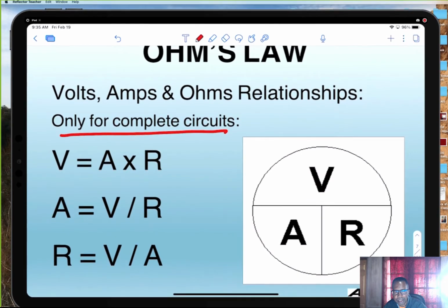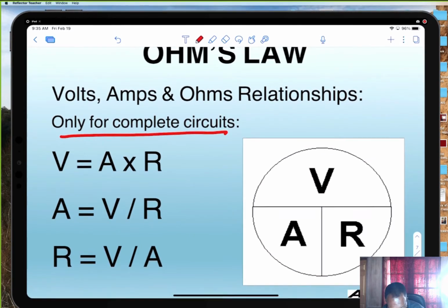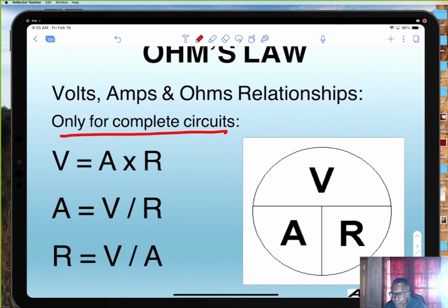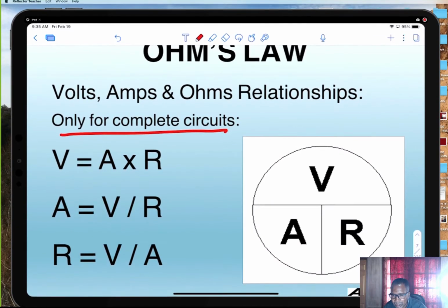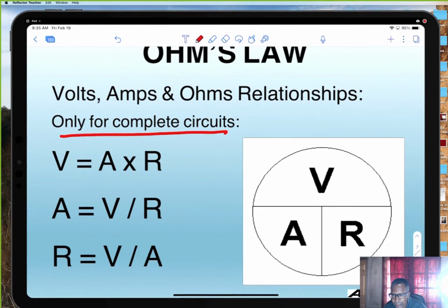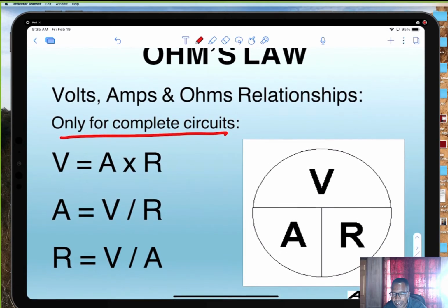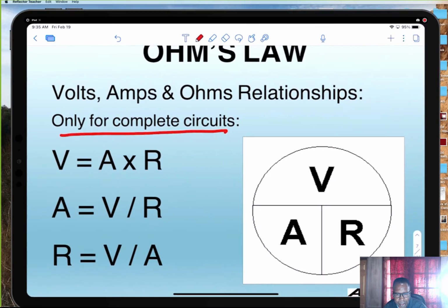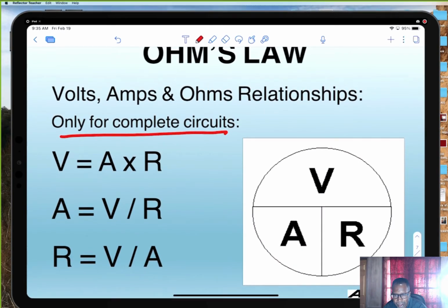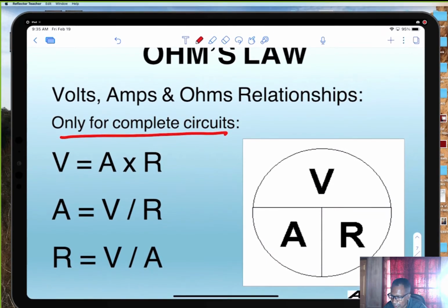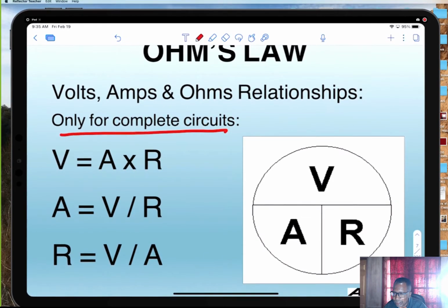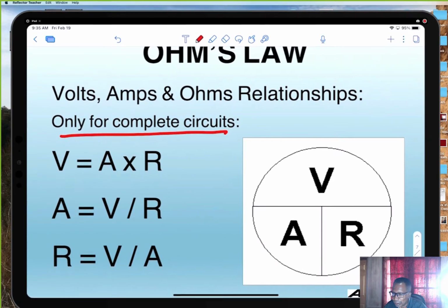A complete circuit is one that doesn't have any opening in it. Exactly. A complete circuit has a path from source to ground. You can have a battery, source voltage, a load device, and a complete path to ground. Now, obviously, in a real circuit, you have switches and other things too, but just a basic circuit has source voltage, a load device, and a complete path to ground. Missing any one of those things, or if it becomes open, you don't have a circuit, and current won't flow.